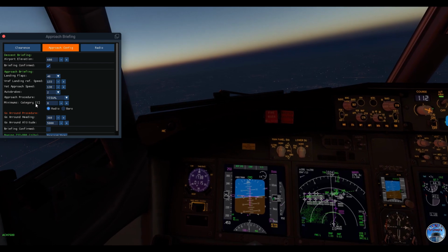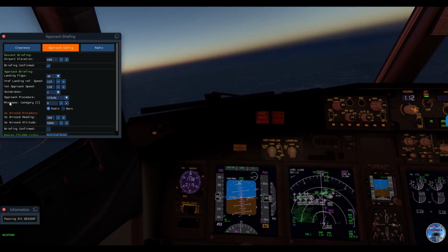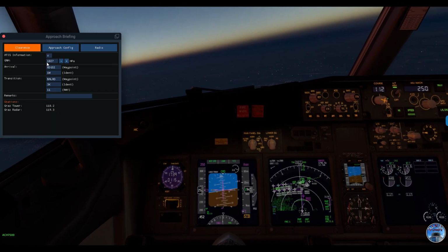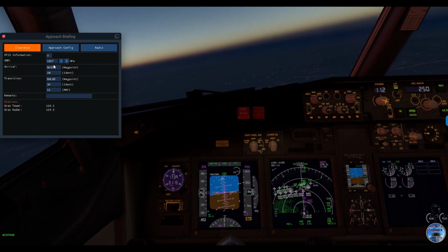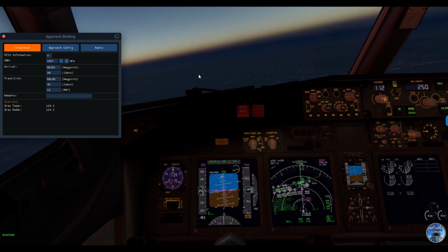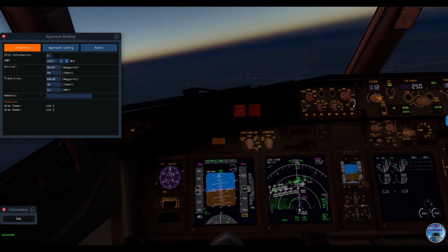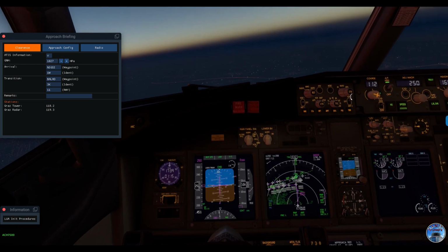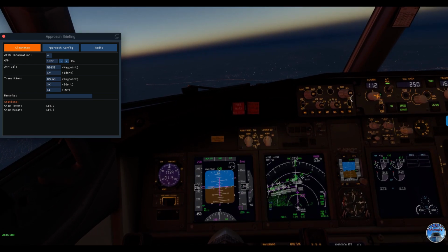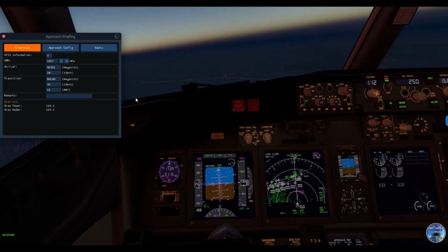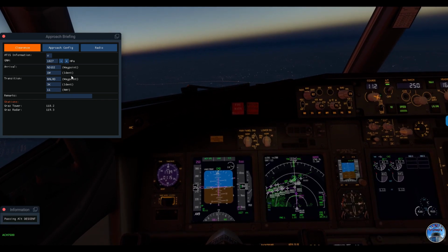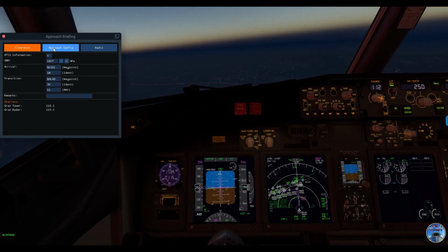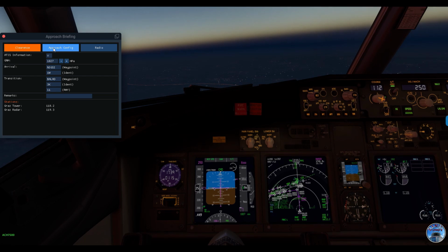The minimums. Passing 10,000 feet. Okay, we are passing also the transition. Passing transition level, check altimeter. We have to set QNH 1027. That we have to do manually in a moment, but that was too much. 1027. Passing 10,000 feet. Okay. Passing transition level, check altimeter. Checked.